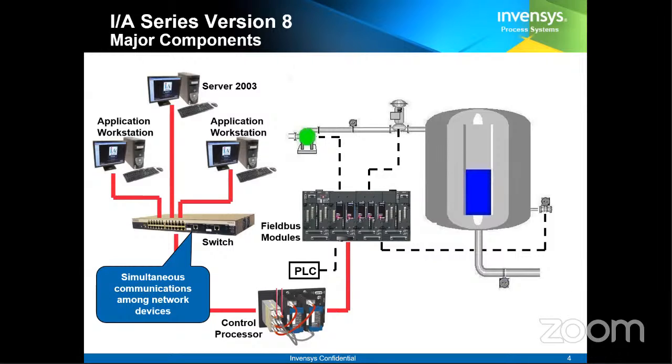So these workstations need to be installed with a lot of software. DCS is not just using the software. When you are going to develop a DCS system, ultimately the DCS engineer is going to install all the software. These software are not just a simple exe file. They come with a lot of SQL database installation, then Visual Studio installation, and then the DCS installation. And depending upon the different DCS system, the installation procedures will be different.